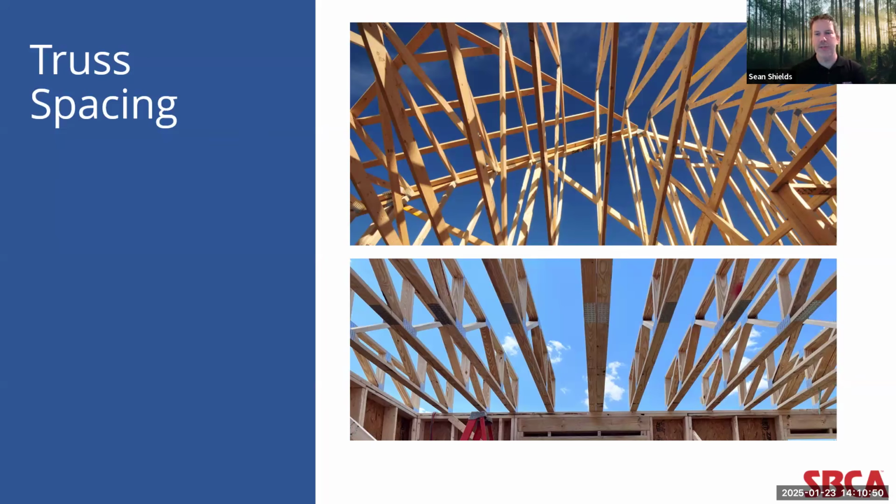Now, for most residential and light commercial application, truss spacing is 2 feet on center. Typically, the component manufacturer will work with the customer to determine their desired truss spacing. Again, this is typically 2 feet on center, but for, let's say, agricultural applications like post-frame construction, trusses may be spaced anywhere from 4 feet to 16 feet on center.